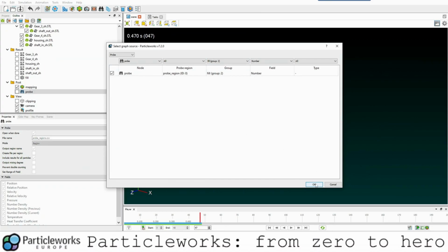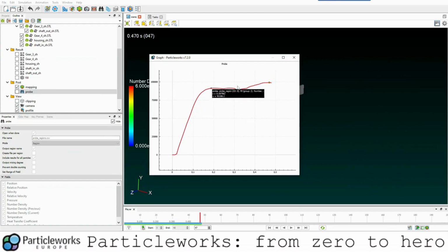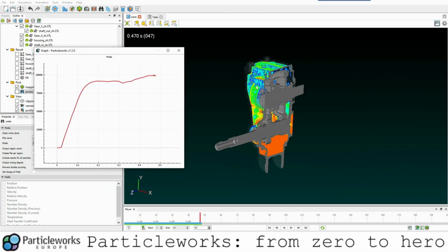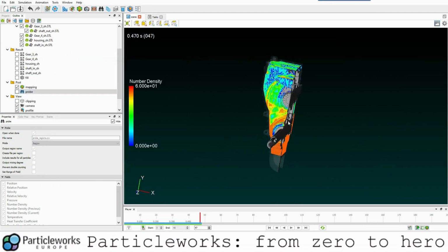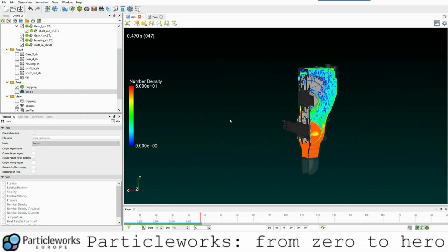Okay, so it's connected with the amount of oil, and I will see exactly that after 0.2 seconds, basically the amount of particles, so the volume in the region above a certain level, has reached a stability. Okay, so this can also help me in understanding if a simulation stabilized with respect to the flow distribution.